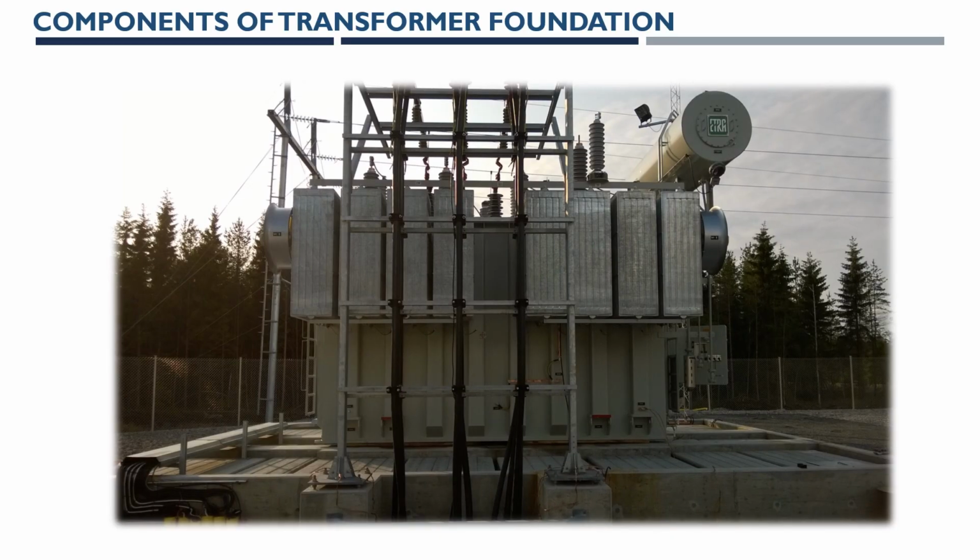This is a complete transformer foundation which is laid over the foundations, having a cable support. You can see here this is a cable support which is mounted on the bund wall by providing a cantilever column, or an extended column from the bund wall, and these are the hauling beam and the jack pad here.